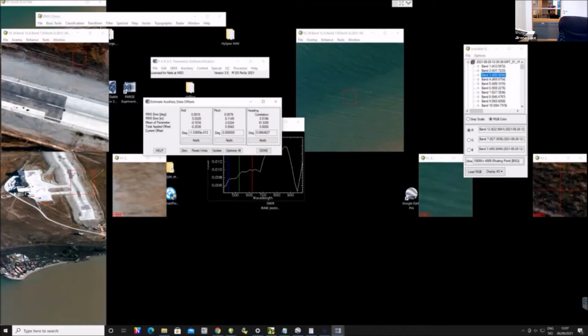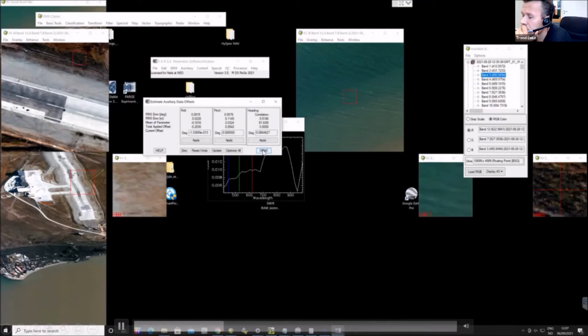For this area here, as I said, you can get the Boresight very good, because here you have the same height reference. Here you use the EGM 2008, both for the navigation data and for the surface model made by the phase one. For the other area we flew, it's in the Svalbard grid, so there will be an offset. That's also something you can apply if you know the offset.